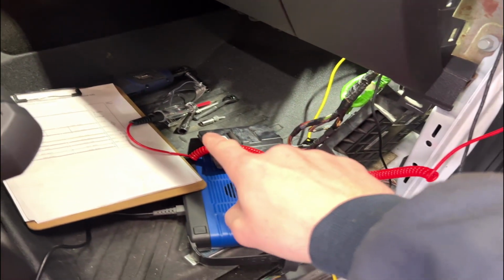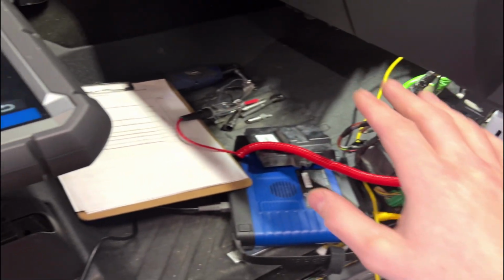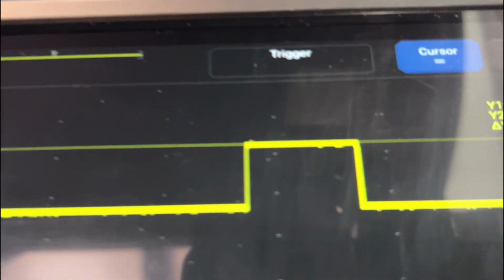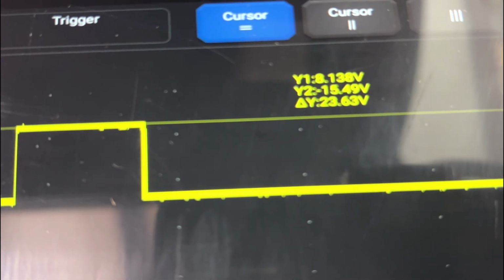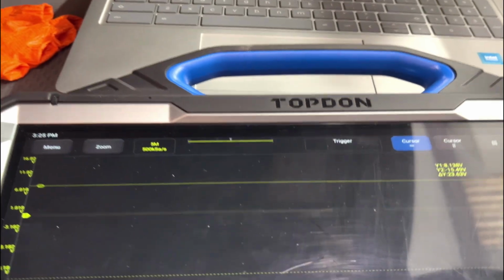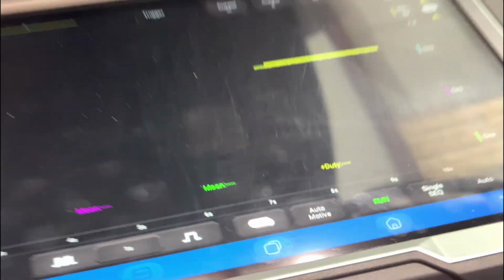I really like LED test lights for stuff like this. For sense circuits, they're amazing. They're great for it. Figure out what that voltage is right there. Y1, you're looking at about 8 volts, just standard switch stuff. But let that rerun, turn that off.